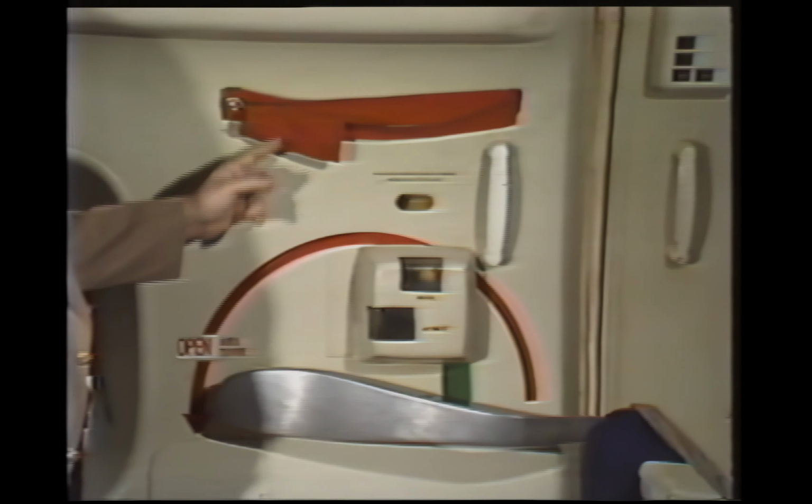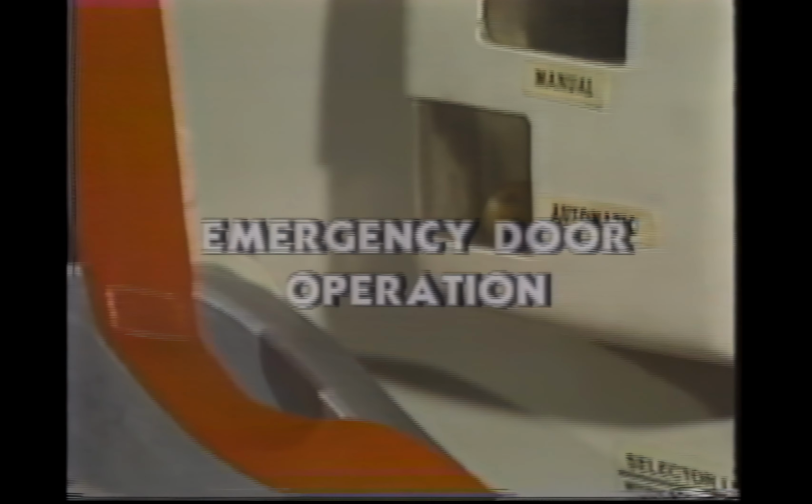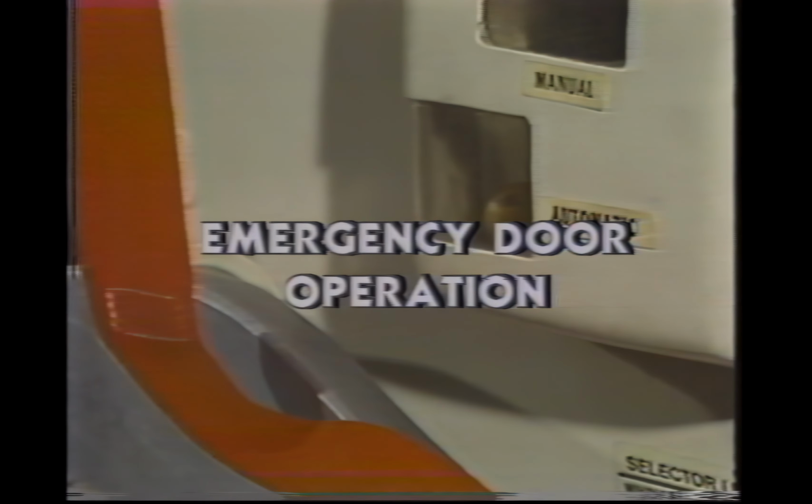There are several door pre-flight items. First, check the red warning ribbon in the stowed position and raise the cover to check that the door safety pin has been inserted. Check the slide raft pressure gauge located in the slide raft housing to see that the needle is pointing in the green zone. And check the door power assist pressure gauge, which is located just forward of the door, to see that the needle is pointing in the green zone. With the mode selector handle in automatic, the slide raft inflation and power assist features are armed and ready for an emergency.